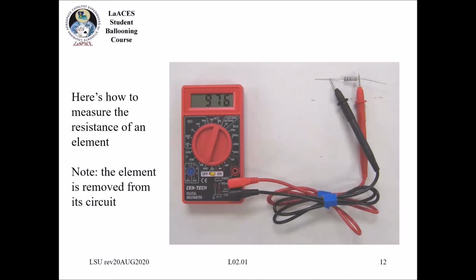And to measure the resistance, we're still on our voltage, resistance, milliamp lead here as well. It's also important, and I didn't point this out between the last two, that you have to turn the dial to actually read these different things that we're talking about. So when you're measuring voltage, you're going to be putting it on the DCV range. When we did the current, it's DCA. And then for this particular thing, we've got the dial set to resistance.